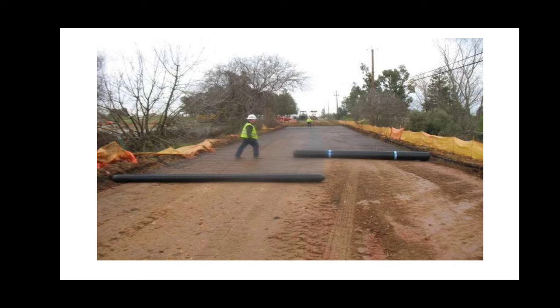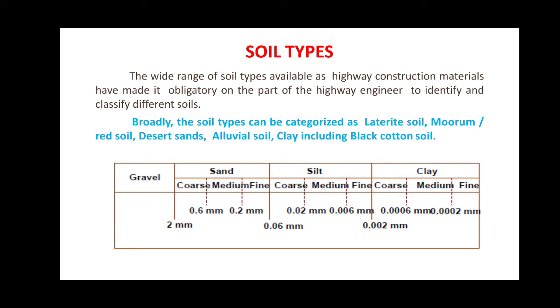From the figure, we can see the preparation of the subgrade soil. It has to be compacted well, and efficient material shall be used in order to drain out the water from the above layers.